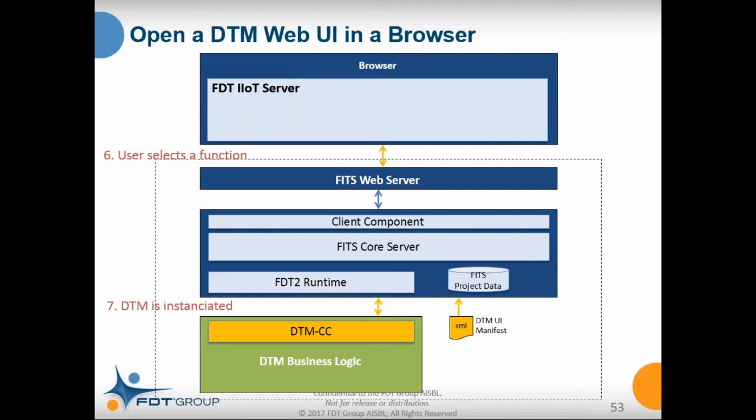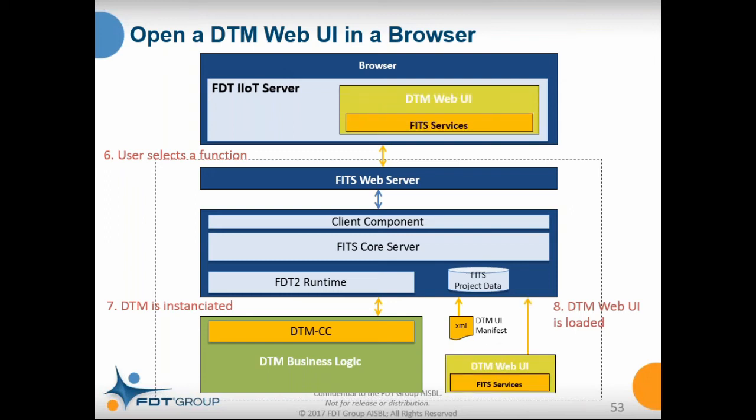And now at this place, actually the DTM gets instantiated by the server. So first, the server starts this FDT2 runtime process if it is not started already, and it instantiates the corresponding DTM business logic. Then, as I said, the web UI is registered by this DTM UI manifest to the server.